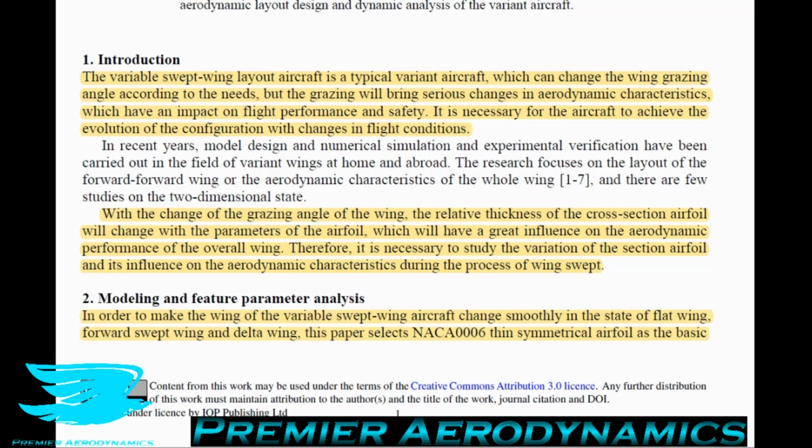Imagine you have a regular straight wing, and you have a regular airfoil profile. Let's say a NACA 0020, so a very simple, common, thick airfoil shape. Let's say the wing chord is 1 meter. If you then pull the wing back at a 45-degree angle, that wing chord will now be, I think, 1.414 meters from basic trigonometric principles. So the chord is longer because the chord is measured from the leading edge to the trailing edge in a straight line of the free stream direction.